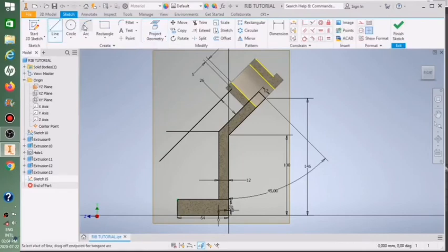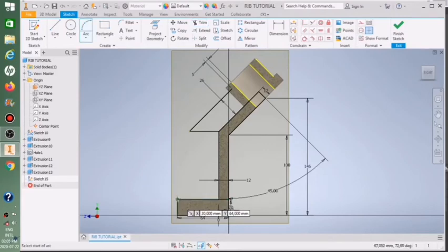and then we click a 3-point arc, and then okay, in order for us to see what we do, let's escape there and first trim these pieces. Now we'll be able to see what we do where we're sitting with our 3-point arc. We click on our 3-point arc, and then we click on there, first point, second point, third point. That's our 3-point arc, and then we want that radius to sit at 55